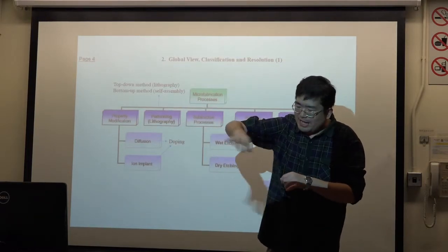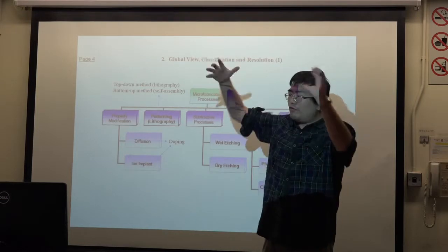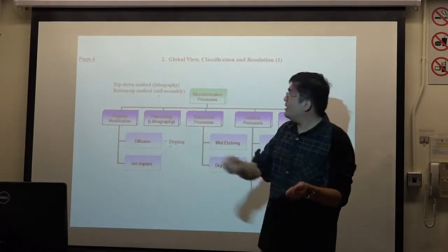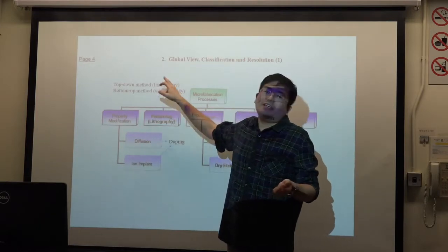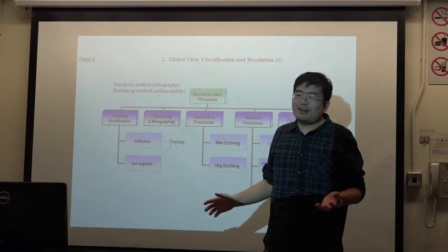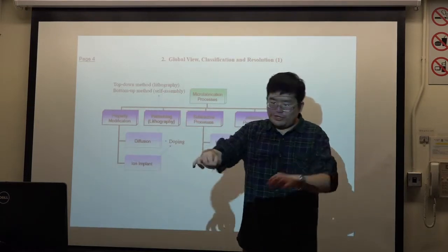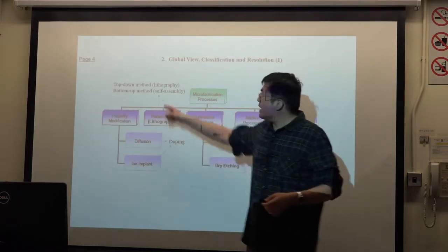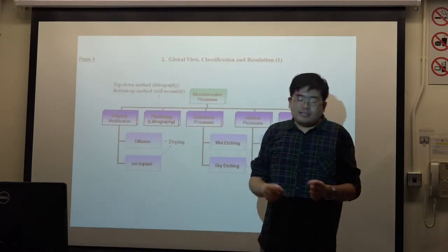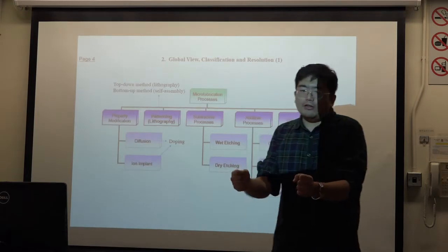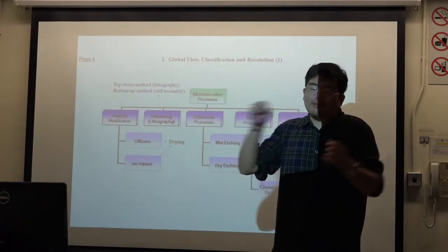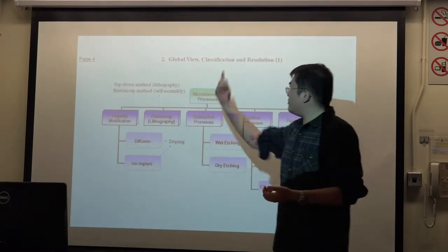Okay, just make them with patterning, from a large scale to a small scale. We call it top down, like optical lithography, E-beam lithography, ion beam lithography, many lithography. Just take the bulk material and cut. Another is the bottom up method. We call it self-assembly. They use very small particles and assemble them into the large scale. They go from small to large. Okay, they call it bottom up.